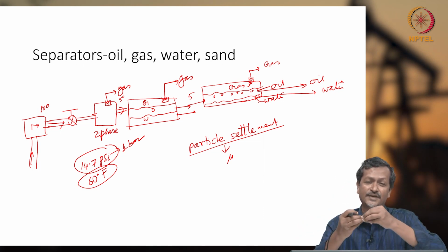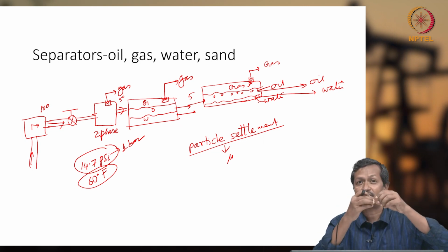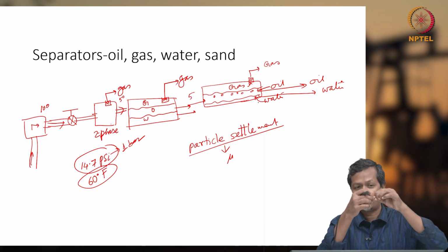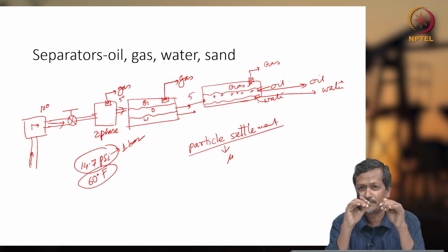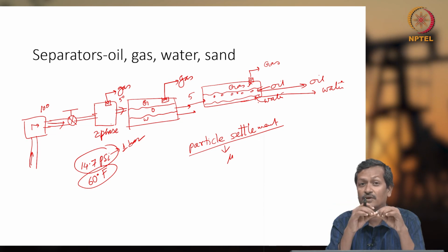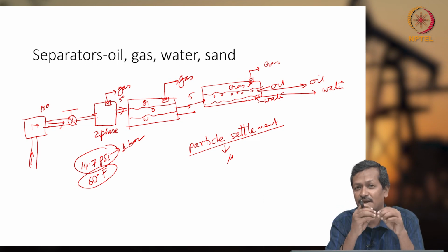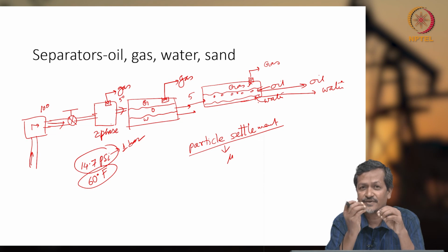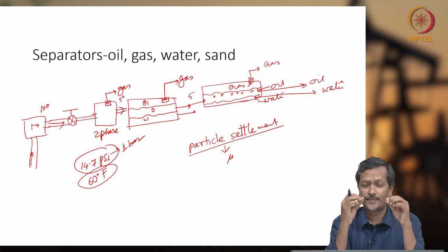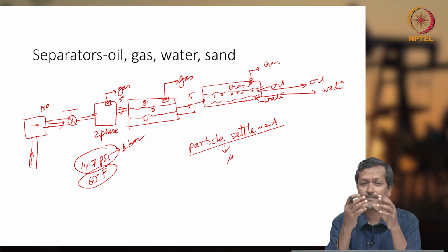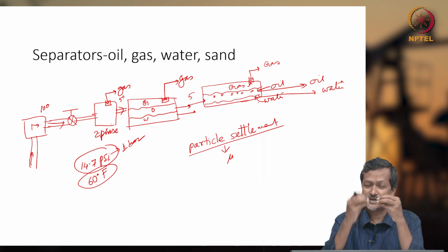But if it is taking a very long time, 2 days, 3 days to settle some particle to the bottom, that means water is mixed in oil, and water is not going quickly. In ideal condition, oil and water will not make any multi-phase situation where water will not settle down. But sometimes some chemicals hinder, for example asphaltene and paraffin. They are surface active agents, so they will not allow the fluid or water particles to collide with each other and make bigger particles. If you have bigger water particles, the settlement rate will be higher.